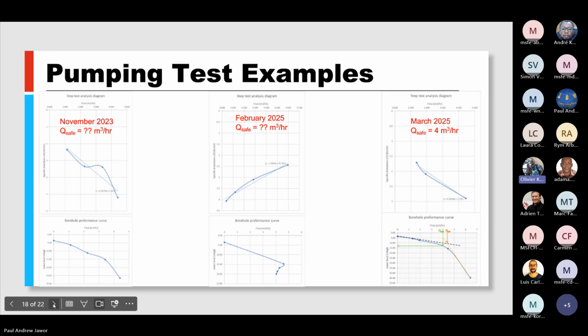If your curve does not have this shape, because it represents progressive pumping, progressive in the sense of an increase in the flow rate, then that causes a progressive increase in the drawdown of the borehole up to a level where, first, the pumping rate is lower than the recharge rate, so the drawdown is relatively little.